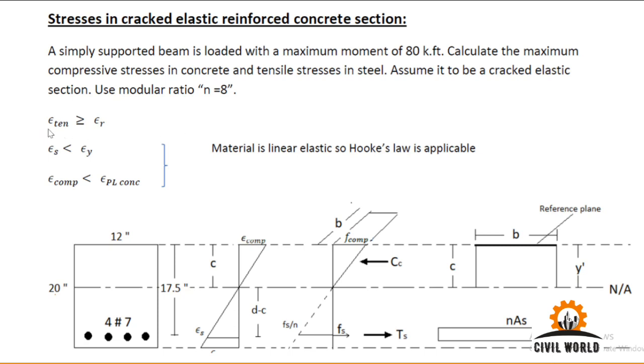So our tensile strain in concrete has already exceeded its cracking strain, so concrete is cracked. The section is in the linear elastic limit, so we can use Hooke's law to calculate our stresses using strains.